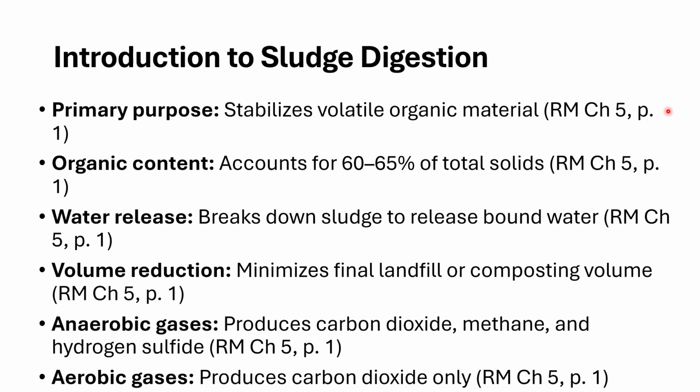We're really slowing the flows down in the primary clarifier, which allows that suspended organic material to settle out and form our sludge blanket. And our sludge blanket is just the suspended material settling out at the bottom of the clarifier. Okay, and we also have some scum floating at the top, particularly fats, oils, and greases coming in.